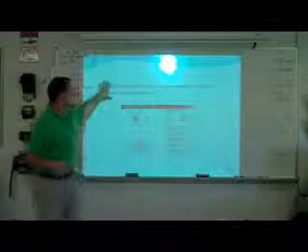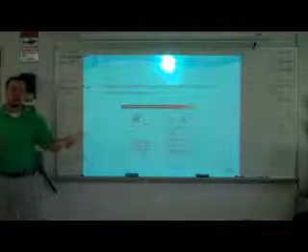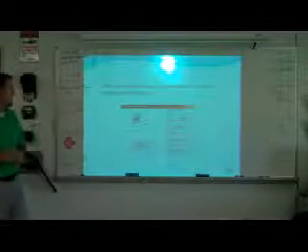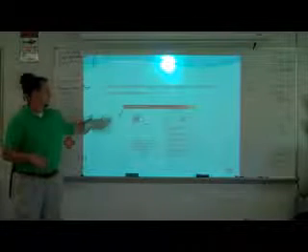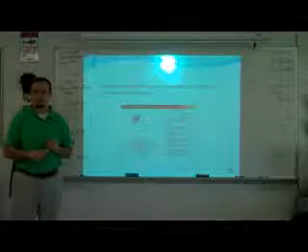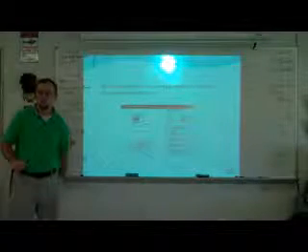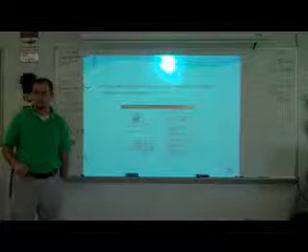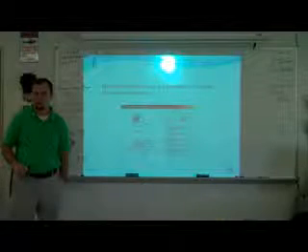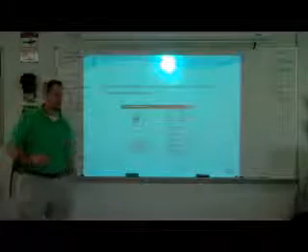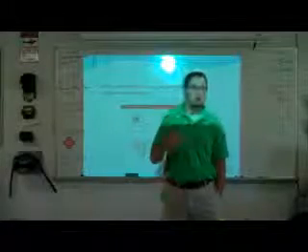This is talking about overcurrent devices. Your breaker panel, your fuse panel. Okay? Are not permitted in closed closets or bathrooms. Why not closed closets? Not always. Closets are kind of a special thing. They can either be calculated as inhabitable or not inhabitable when you're talking about lighting.